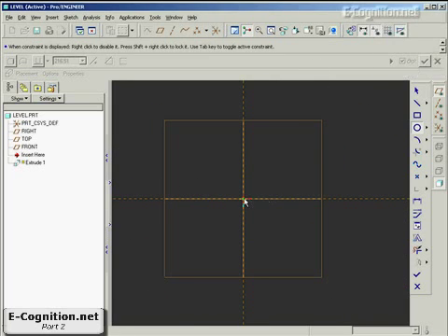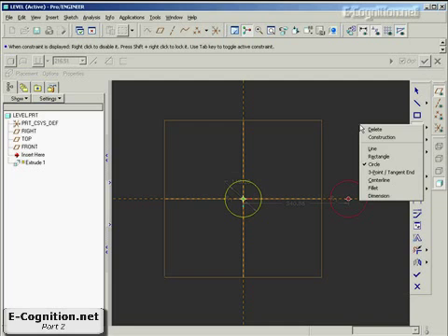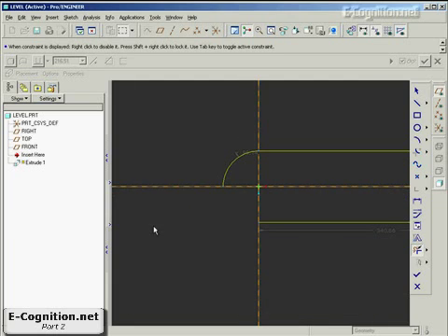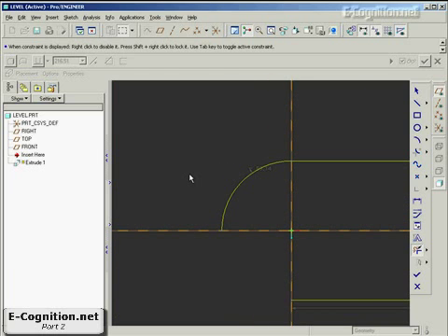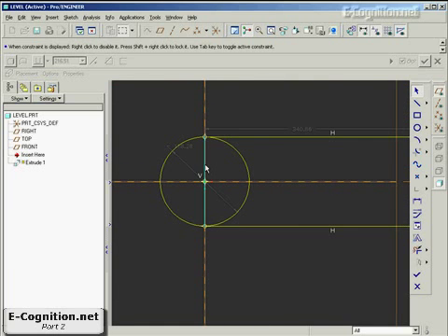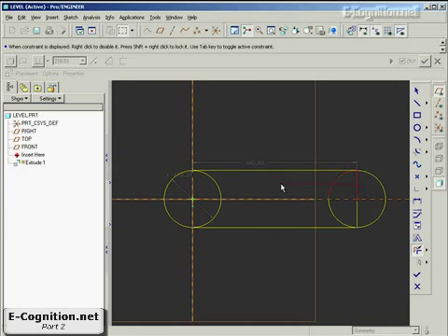I'm going to have a circle for the end of the plate and a circle for the other end of the plate. I'll right click for a rectangle, and starting here, drag it out to here, and then using my squiggle trim, I'll just click and drag right around that racetrack. Whoa! Did that ever happen to you? It's missing a part. Control Z. Okay, so why did that happen, and how do I keep that from happening? Pick here, delete this piece, and then do the squiggle trim. Let's try that. Kind of a pain, but there you go.